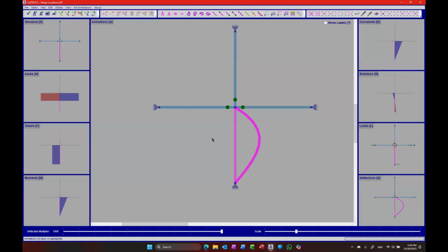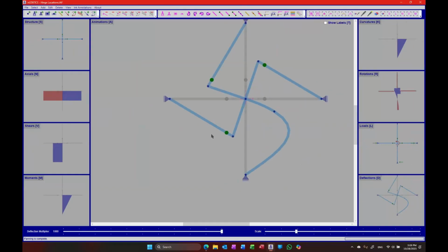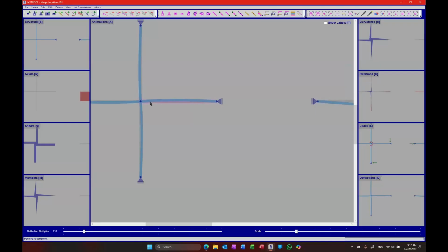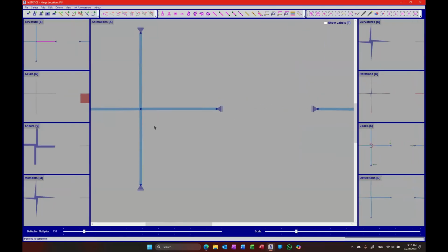Now, what happens if I turn also this into a hinge? Now I got, sorry, let me just do the second one. Yeah, now I got a singular structure, so I can't get a result. Why? Because this joint is now free to rotate as it pleases, right? So to simulate this, I created something here that basically includes these short links where the joint is a separate structure. So instead of having a zero offset for the hinges, right? I made them, let me make these the same again so you can compare those.